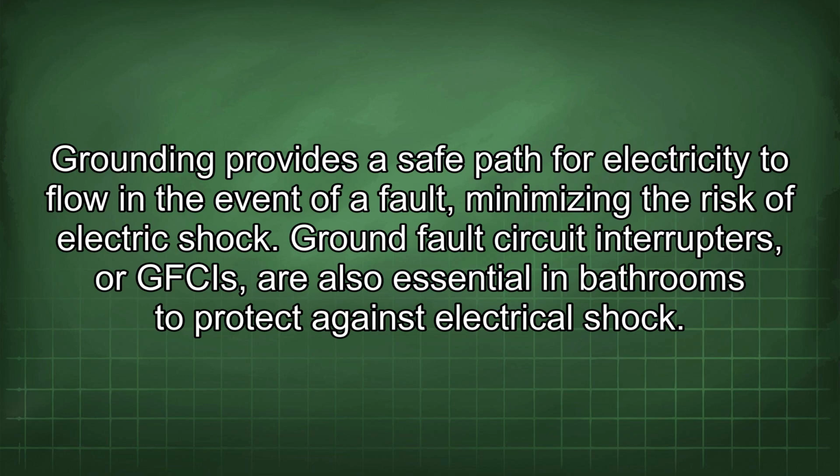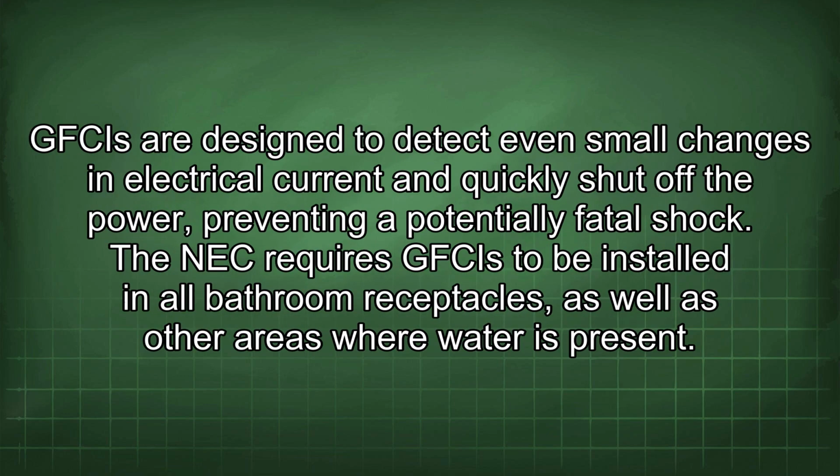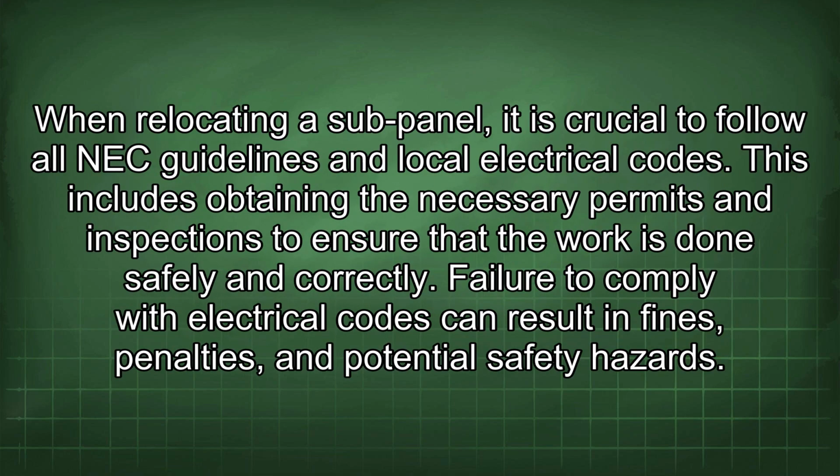of electric shock. Ground fault circuit interrupters, or GFCIs, are also essential in bathrooms to protect against electrical shock. GFCIs are designed to detect even small changes in electrical current and quickly shut off the power, preventing a potentially fatal shock. The NEC requires GFCIs to be installed in all bathroom receptacles as well as other areas where water is present. When relocating a sub-panel, it is crucial to follow all NEC guidelines and local electrical codes.